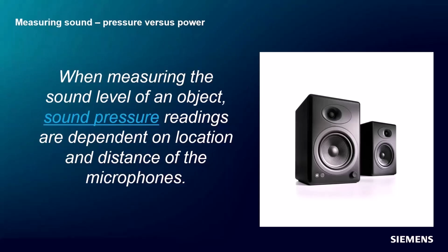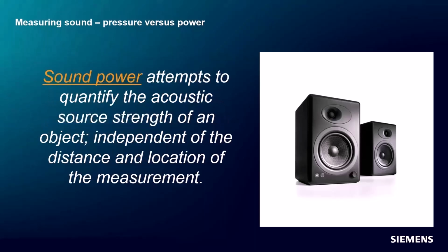Now, on the other hand, sound power is the total amount of sound energy that is radiated from the source. So it is independent of the distance you are measuring and the location you are measuring, because it's the total amount of sound energy radiated by the source. You can use sound pressure measurements to calculate sound power, and that will be the focus of this presentation.